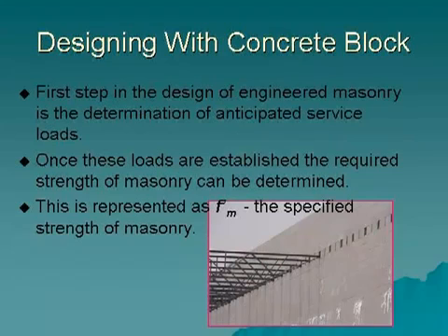Consider that the first step in the design of engineered masonry is the determination of anticipated service loads. Once these loads are established, the required strength of masonry can be determined. This is represented as F'm, the specified strength of masonry.